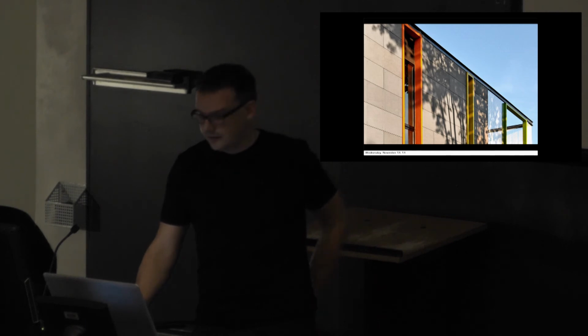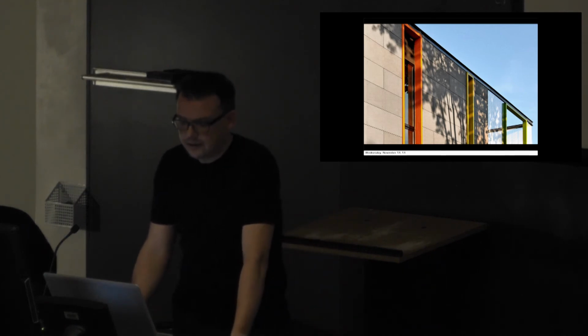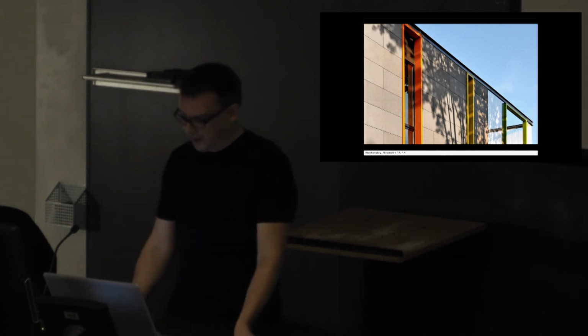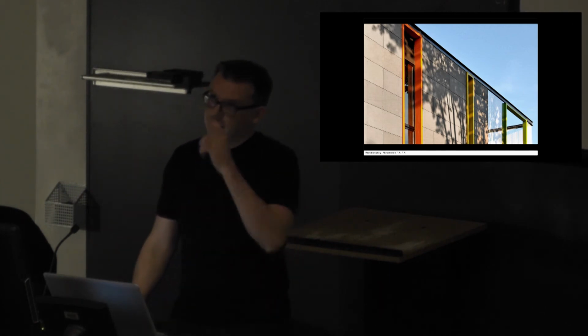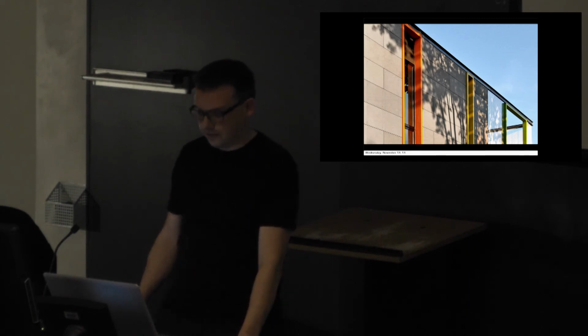Rainwater is harvested. And then we designed this pretty sophisticated envelope that achieves an R value of 36. It's a ventilated rain screen facade with an 8-inch deep cavity that's behind these concrete fiber panels. And then we insulated it with expanding soy-based foam insulation.